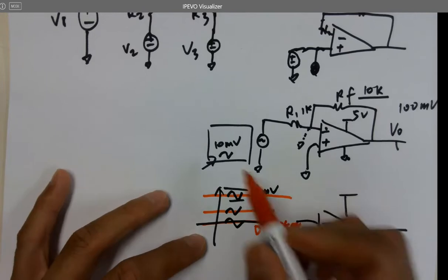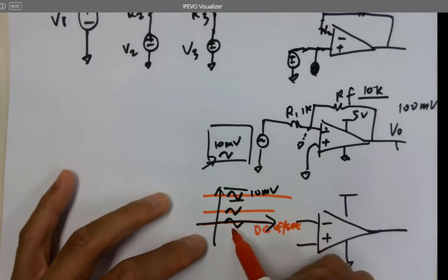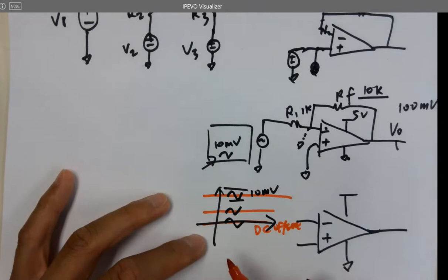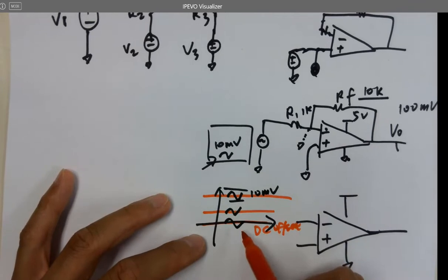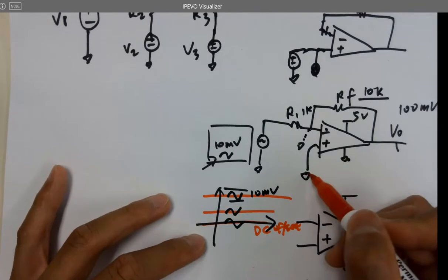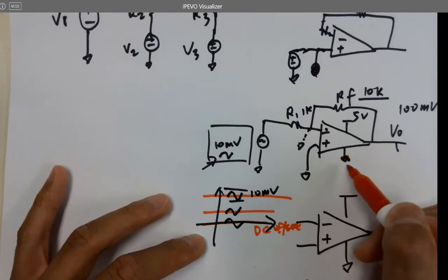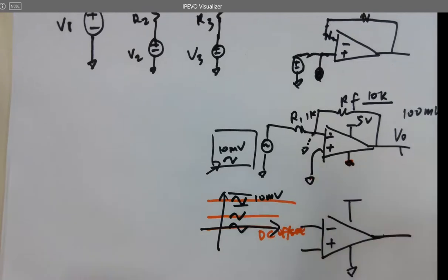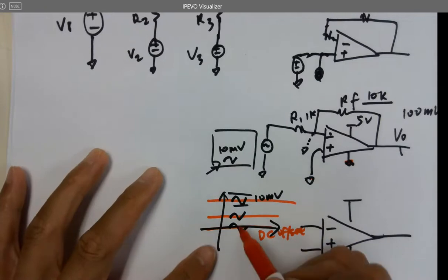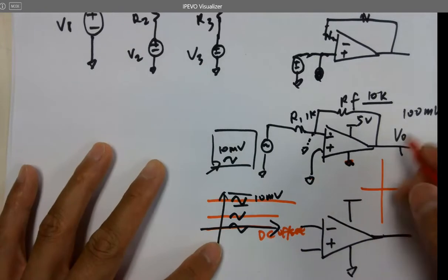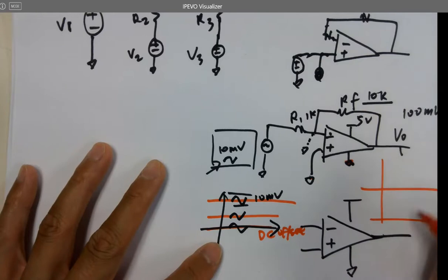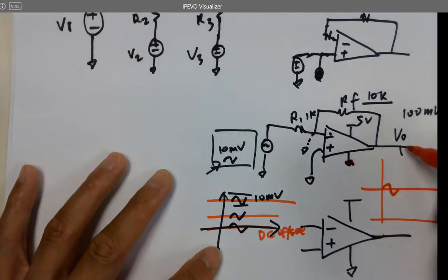0. If you do not do anything to it, the default DC offset is going to be 0. It's going to swing to negative voltage. So do you have a negative rail here? That's the lowest potential in the circuit. You won't be able to see any negative voltage. So what's going to happen is, ideally, here's the input, here's the output. Your input is like that. No problem, you can probe it. You can show the negative voltage on the oscilloscope.